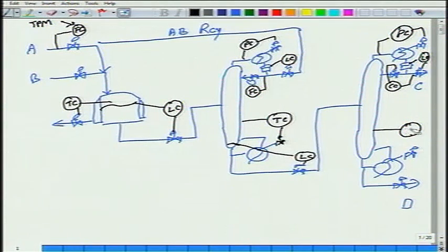Well, we discussed this last time. In the absence of any other information, it should be done this way, because the boil up is the larger stream and the bottoms is a leak, and that leak, once the temperature controller is switched off, won't be enough to control the level, right? So we'll do it this way anyway.